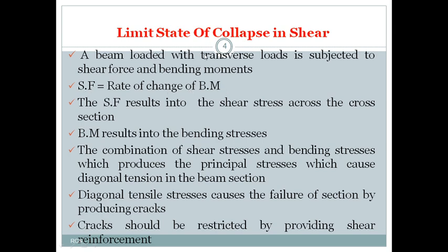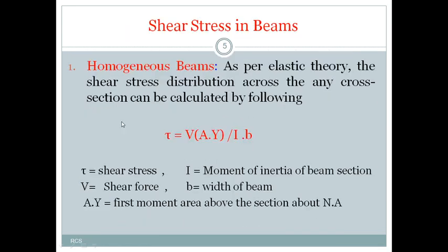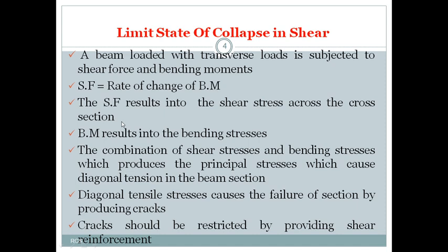So when you apply the load, there may be a chance of shear forces occurring. These shear forces will result in shear stress across the section, right? And along with the shear force, a bending moment also occurs. That bending moment results in bending stresses in the beam.